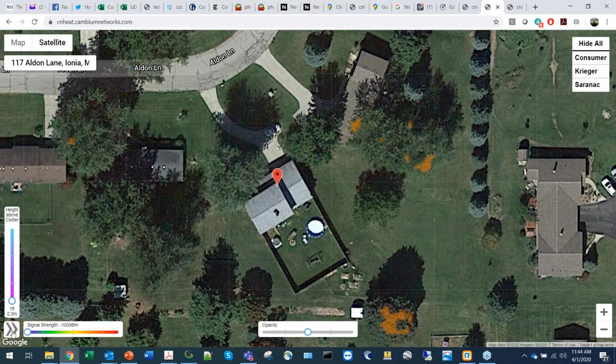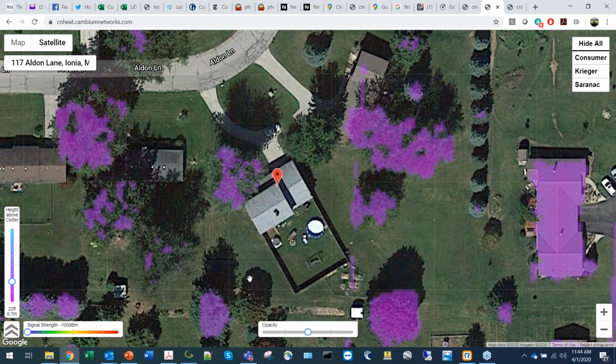Let's look at this in height mode. And that's just, instead of showing it in RSSI, we'll show it in the height that the coverage is at. So I simply move this slider up, and I get to a certain spot, like at 21 feet, and there starts to be coverage in a line right here. So if I go quickly back and forth, you can see it in the bright RSSI mode. I go to the height mode, and we go back, and there's coverage starting around 21 feet.